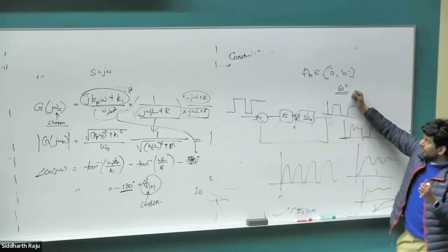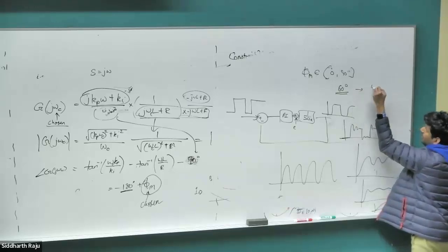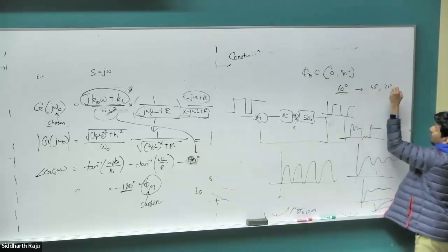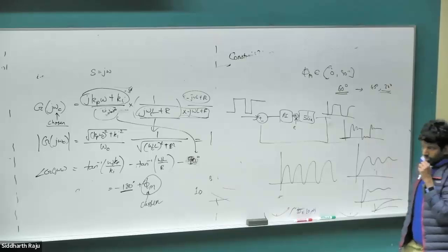If you are doing online parameter estimation, you have a good model of your system, and you can push this value much lower, even to 45 degrees or 30 degrees, which would make it go from the overdamped case to this kind of more oscillatory behavior. What do we get by going to this more oscillatory behavior?